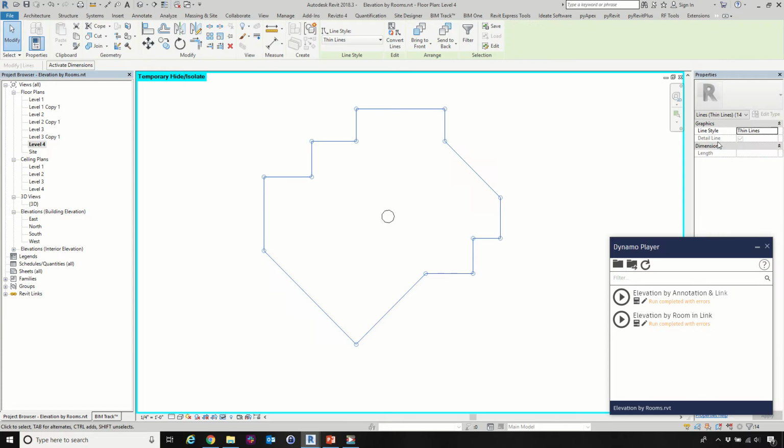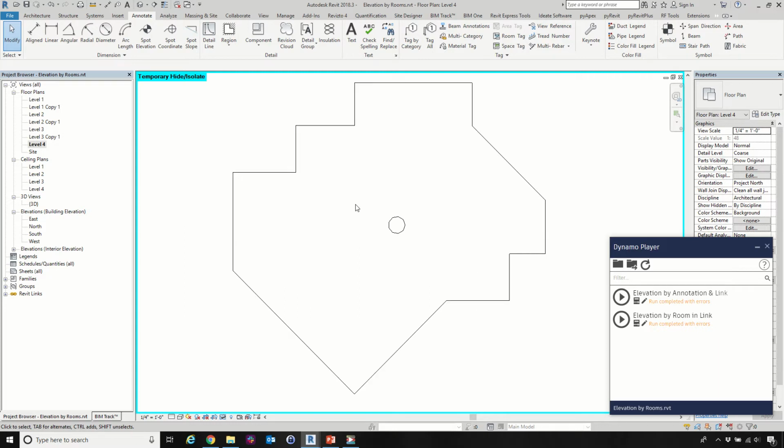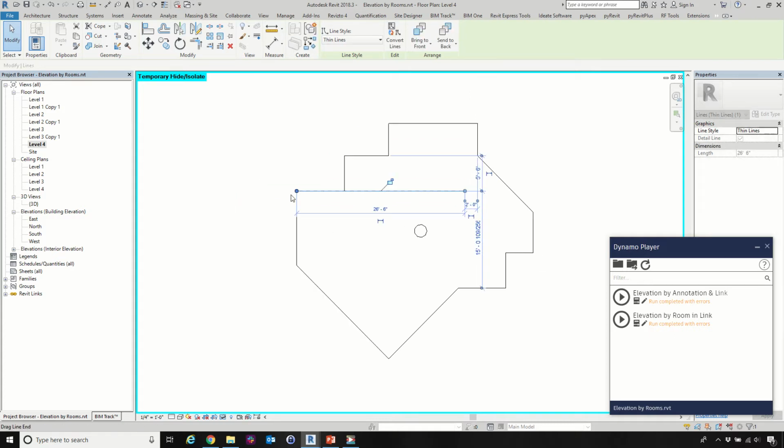Now this room is a combination of 14 individual lines, but we only need 2 elevation markers and in total 7 elevations. So we need to group these lines. How do we group them? Well, we start by trying to find the perpendicular vector from the room location to this curve. How do we do that? Well, we take this curve. It could be going from here to there or going the other way from here to there. So we extend the curve by a really long distance.